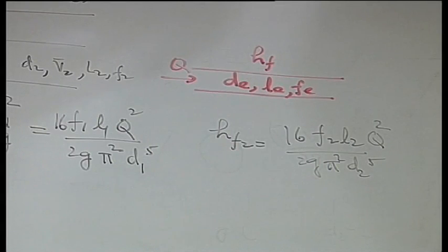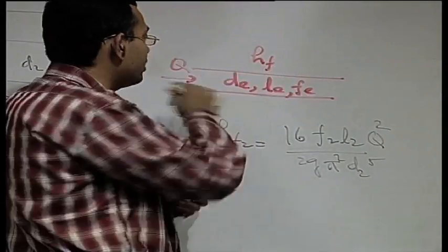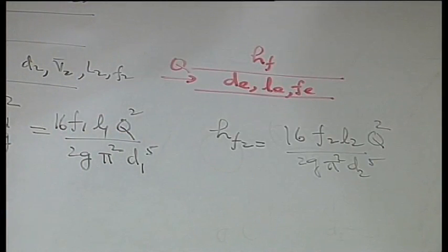It is just like an electrical circuit where you consider the same voltage and same current flowing through, so you find an equivalent resistance. Here the head loss is like the pressure drop, which is like a potential drop, and the flow rate is like a current, so to say. It is not exactly analogous mathematically, but it is just another qualitative way of looking at it.